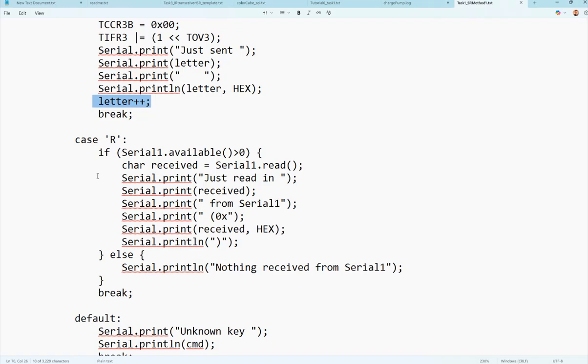Task 1, we don't have ISR for UART1's receiving module. There's no receiving module's ISR written by itself. However, you are using this read and also this one here to check it. But with everything running behind the scenes, the UART receiving module does use ISR by itself. Okay? It's by default. It uses ISR to receive it. So now let's come back. Just relax, come back.